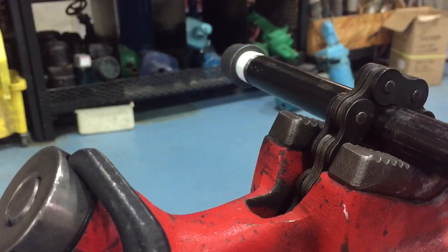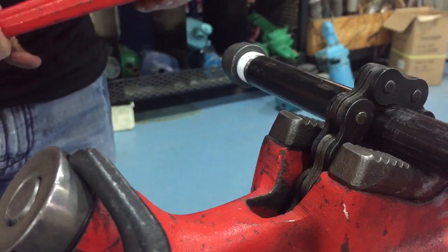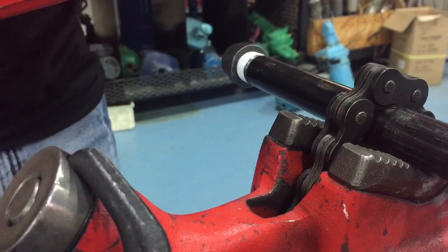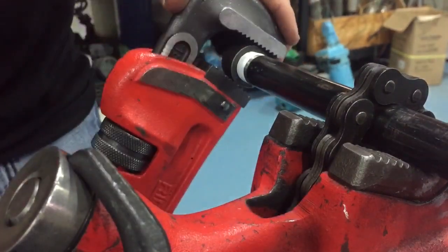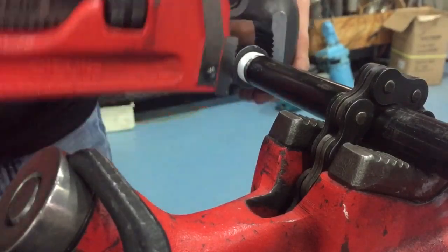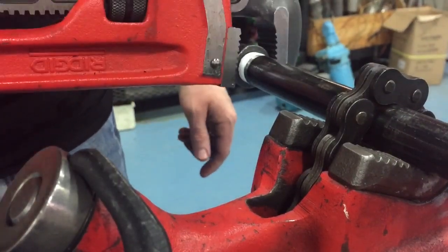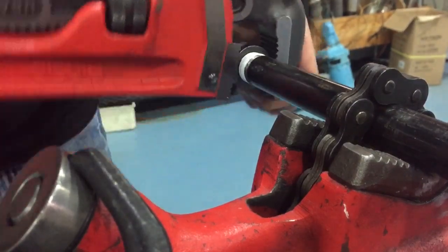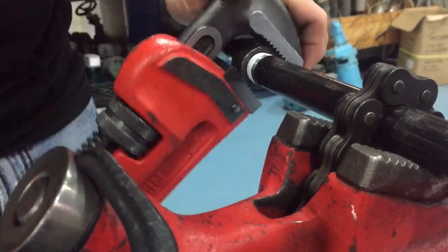I'm just working on my end caps here, putting those on, and just wanted to show a little bit more operation on that pipe wrench. I'm just going to size it up, and the nice thing about a pipe wrench, didn't point this out before, is it has these teeth here, and as I push down, when I come back up, the teeth stop biting. So as I'm pushing down, the teeth will bite, and then they'll stop biting. Just need to make sure you have it sized appropriately, so then it can bite onto the pipe or the fitting, and just push down and keep doing that until you have enough threads engaged.